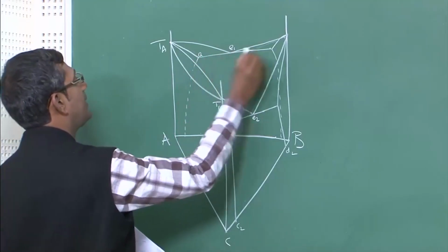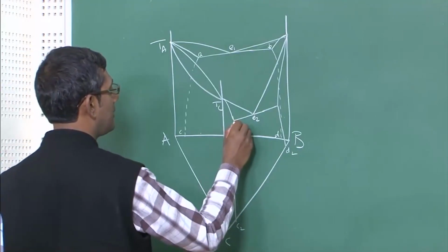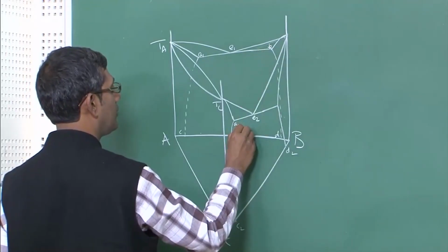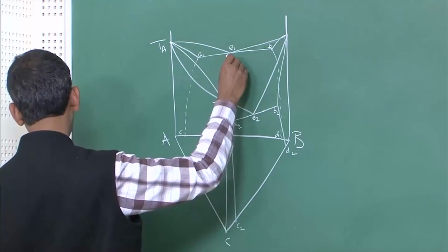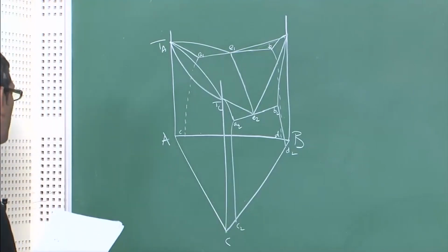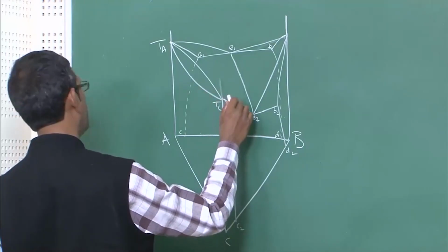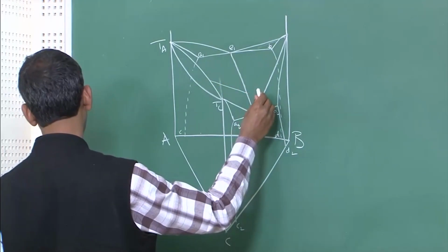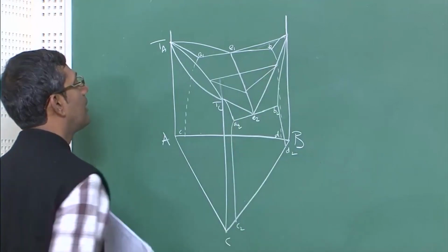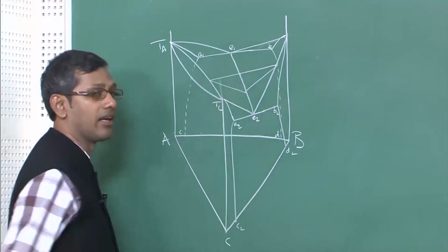I term this A, this is B, C, D, and this is A1 B1, A2 B2, and then I can connect these two eutectics. That is how this phase model will look, and one can generate this triangular region between the three phases alpha, beta, and the liquid, looking like this. So the three-phase region here looks like a triangle.